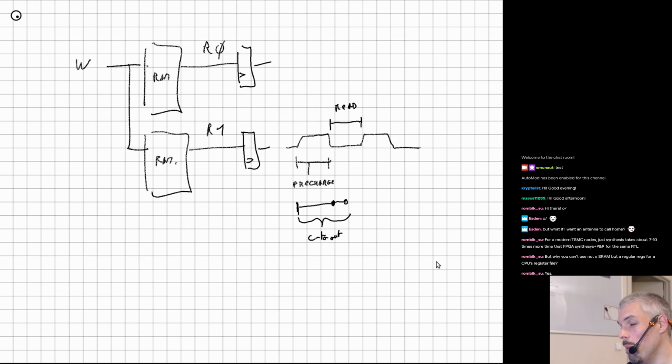Of course, that's a lot of flip-flops, because the design we're working on at the moment is a classic RISC-V, so you have 32 registers of 32 bits, and ideally I'd like a shadow register set for quick swap between interrupt and non-interrupt context, and that's 8,000 flip-flops.